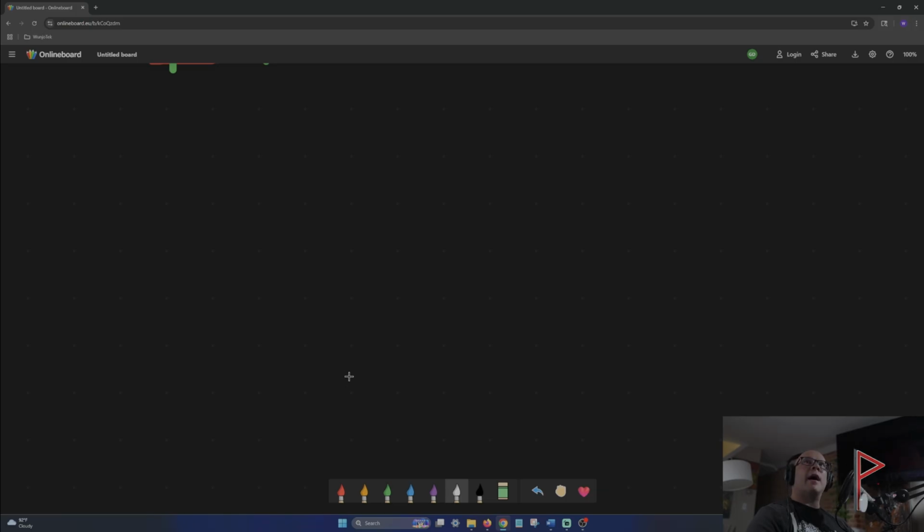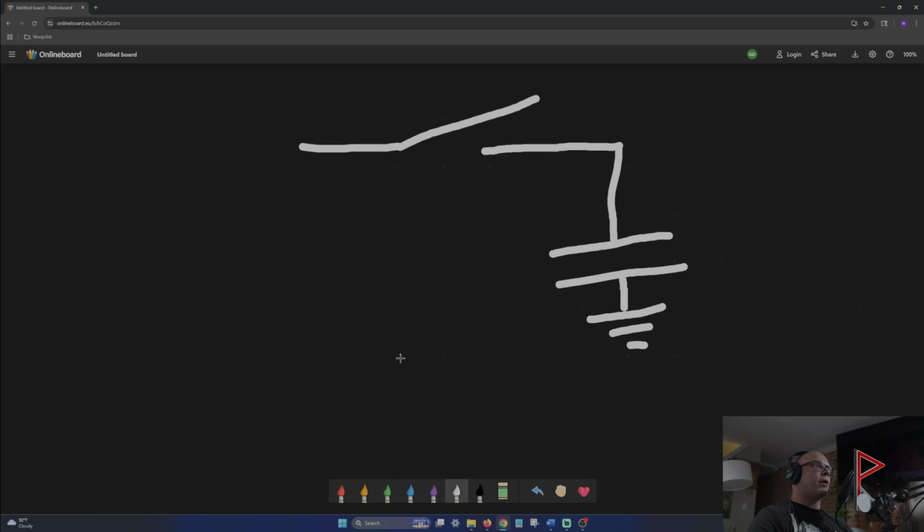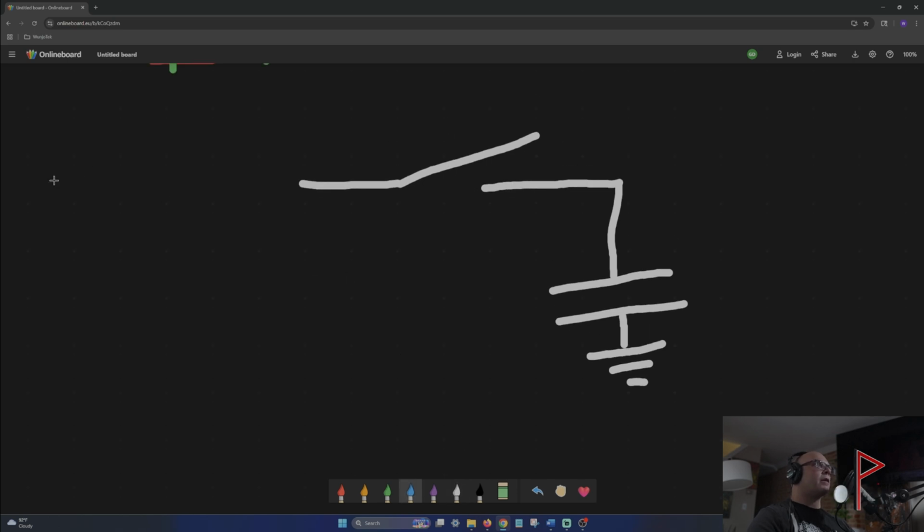So an individual cell might look something like this. You have your transistor, which is connected to your capacitor. And this is a DRAM memory cell. Now, your word lines, let's keep our color codes here, are going in rows, so it's connecting these cells this way.